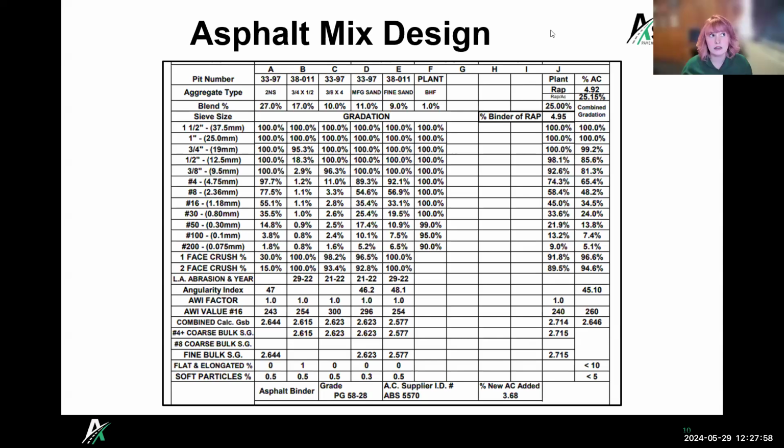Okay. And that is different than your LA abrasion test? Yeah, it's not the same test. LA abrasion is a different test that they use. They test materials, and they have a circular wear track in Lansing where they make these little bricks and run this wheel around and look at how that performs. And so they assign those values as well.